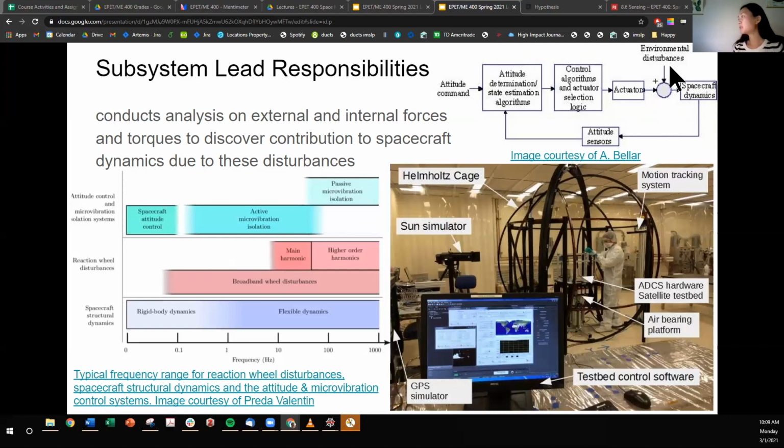So these environmental disturbances, they're not known. They are measured or estimated to a degree. So if they're not known and you have to measure them, then your spacecraft needs to react, which means it measures and then acts post-measurement. If you do know your environmental disturbances, then you can proactively reject those disturbances. So you are adding control before you experience the disturbance itself.